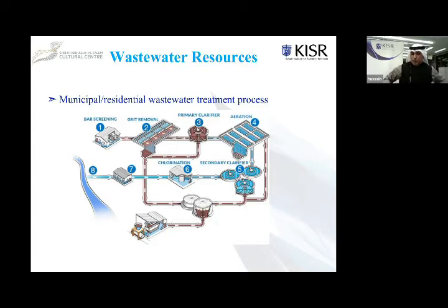What happens here in the biological treatment is that we mix artificial bacteria and activate them with oxygen in the aeration tanks. While they are activated, they consume the organics present in the wastewater. Some of them will settle by gravity, and some will float at the surface of the water, so they need to be clarified in stage number 5, the secondary clarifier, followed by disinfection, usually by the chlorine process or UV ultraviolet light, and then submitted to the distributors, or I mean consumers.